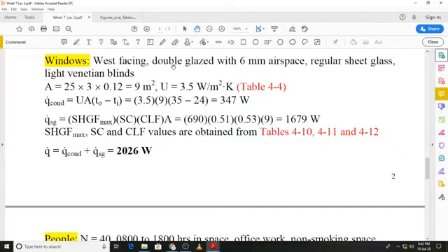see the result of the calculation. So you can see that the heat gain through the wall is 1238 watts. Okay. The CLTD value is 11 degree C. The net area, remember, we have to use the net area. If there is any wall or door in the wall, we have to subtract that area, and then the net area of the wall will be used in this equation.